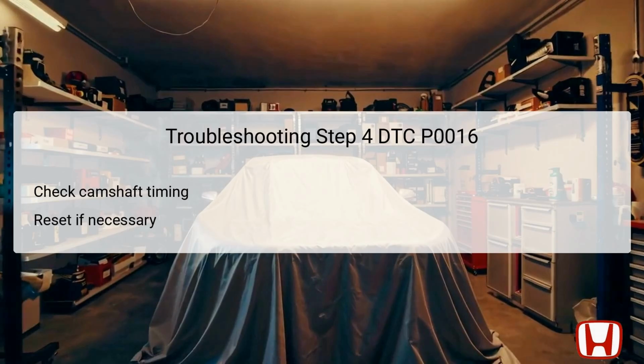Resetting the camshaft timing to the manufacturer's specifications is crucial to restore the synchronized operation needed for the engine to run efficiently. If camshaft timing is confirmed to be correct, the technician can proceed to the next troubleshooting step to further diagnose potential issues. In the fifth troubleshooting step, the focus shifts to the cam chain, which connects the crankshaft to the camshaft, ensuring both components operate in harmony.